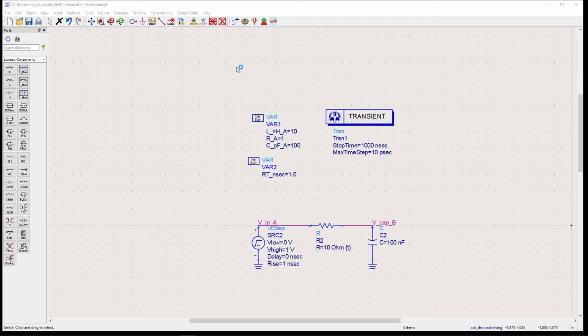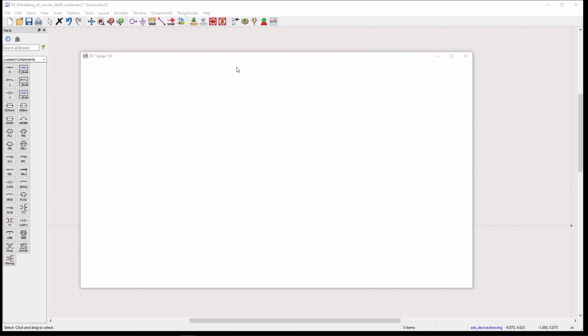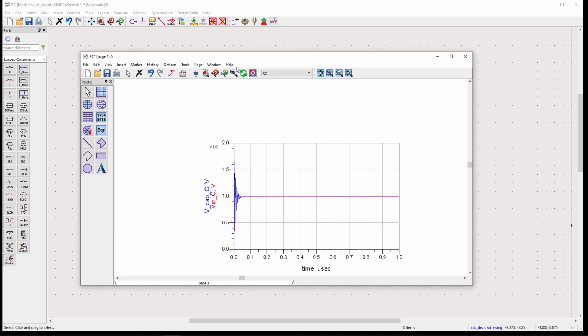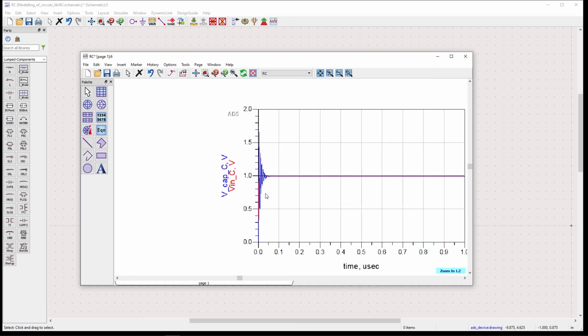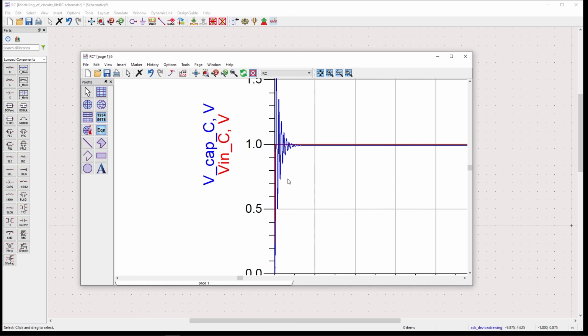Now, this is not the right way to analyze it at all. Ideally, I would do some of the calculations by hand, see what I'm really expecting, do my analysis in MATLAB, see my pole-zero analysis, where you can see a lot of the oscillation, and then get an understanding of what's really going on. Then use the SPICE model to see what the circuit is doing. That's really how I would go about it. Using pen and paper is not a bad thing, especially when you just have resistors and inductors. You can literally hand calculate a lot of this stuff.